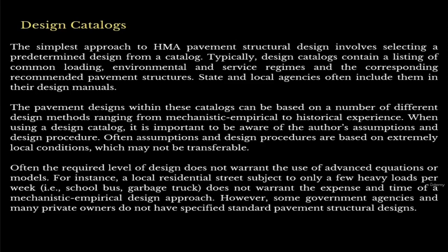Often, the required level of design does not warrant the use of advanced equations or models. For instance, a local residential street subject to only a few heavy loads per week, like a school bus or a garbage truck, or maybe a moving truck when you're moving in and out, doesn't warrant the expense and time of a mechanistic empirical design approach. However, some government agencies and many private owners do not have specified standard pavement structural designs.